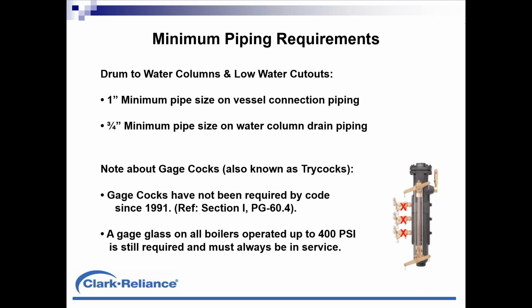Any boilers manufactured in the last couple decades, most manufacturers are not including that additional cost unless it's customer specified. They know the code, and you'd find yourself hard pressed to see the 3 tricocks on a water column on a new boiler installation.